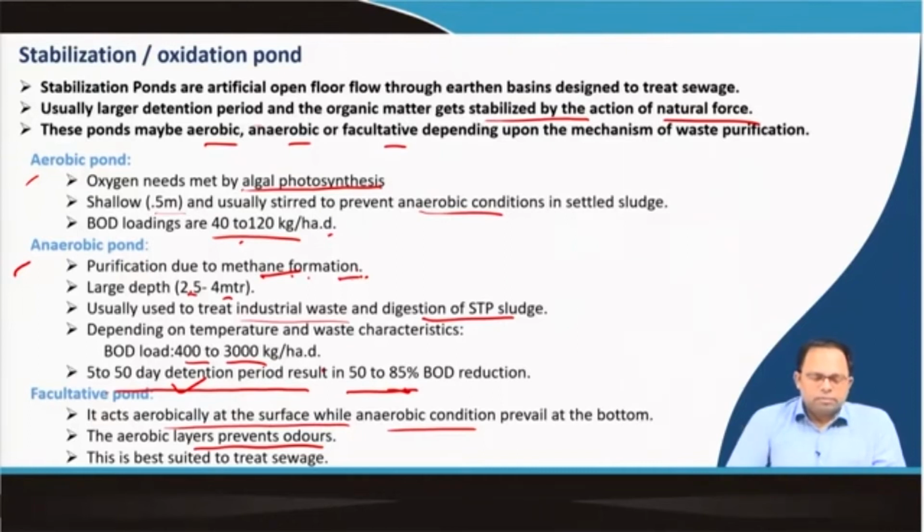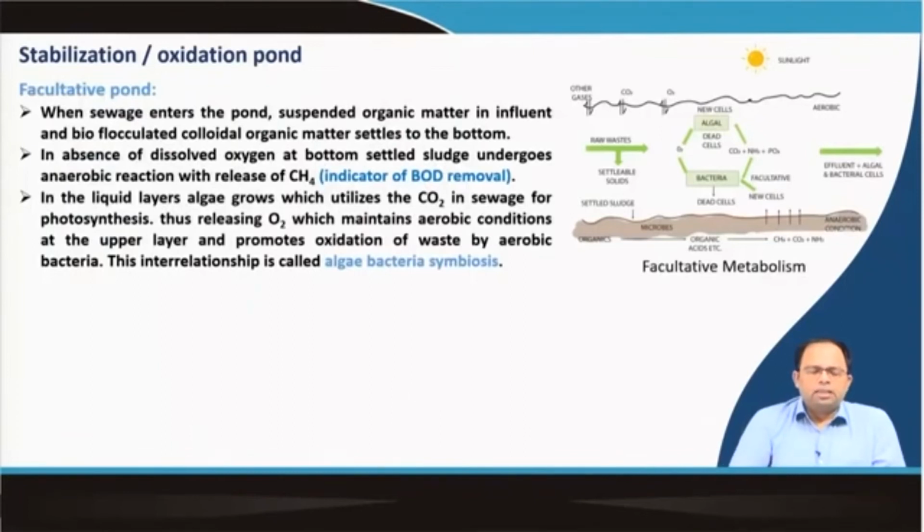stabilization. So, facultative ponds are the best system that is possible, and here the sewage enters the pond, and suspended organic matter in the influent and bioflocculated colloidal organic matter settles to the bottom. So, that means in any kind of stabilization pond, there is sedimentation, naturally occurring chemical sedimentation, that is, bioflocculated colloidal organic matter also settles, and in the absence of dissolved oxygen at the bottom, that is why we see that anaerobic reactions take place and CH4 is released,